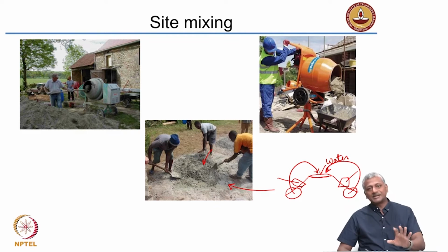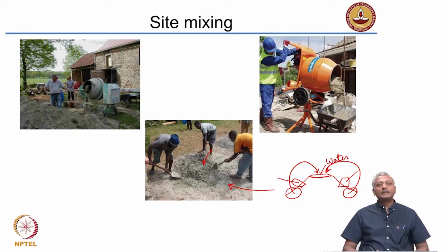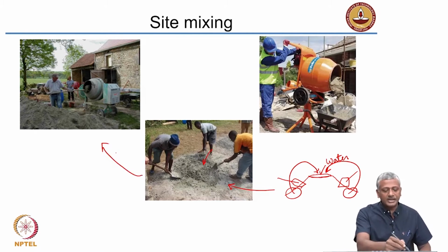Of course, a seasoned hand can actually do a good job at this and make good quality concrete even with simple shovel-based mixing. Okay. But this is not something that you want at a proper construction site where you need good control on the quality of the concrete. In most cases of volume batching, these are the kinds of facilities that will be there. Or, slightly more advanced, what this guy is doing here is he has all the material stacked up, taking a shovel, and directly putting it into this mixer.